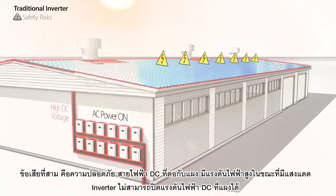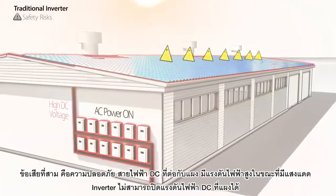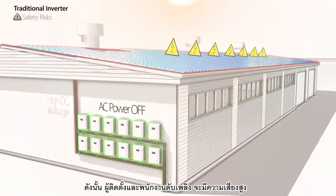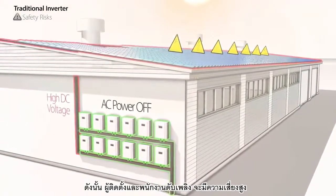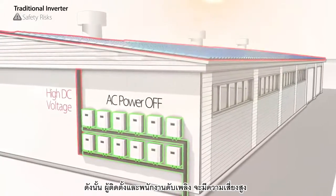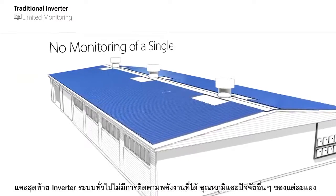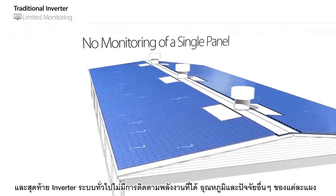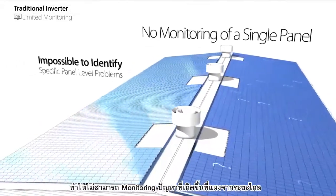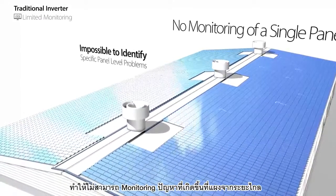The DC cables that connect the panels to a string carry high voltage as long as the sun is shining. The traditional inverter cannot shut down the DC voltage of the panels, and therefore there are serious associated risks for installers and firefighters. And lastly, a traditional system cannot track power output, temperature, or any other parameter of a single panel. This makes it impossible to identify specific panel-level problems remotely.